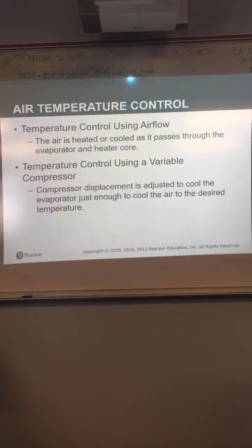All right, air temperature control. Temperature control using airflow: air is heated or cooled as it passes through the evaporator and heater core. Temperature control using a variable compressor. Remember the variable compressor? There was a positive displacement and variable. The compressor will displace, adjusted to cool the evaporator just enough to cool the air to the desired temperature.